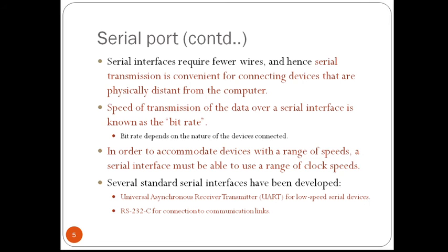After receiving one character from the serial line, the device cannot start receiving the next character until the processor reads the contents of the data in register. As soon as one character is received, the device cannot receive another until the processor reads it. Thus a pause would be needed between two characters to allow the processor to read the input data. Once one character is fetched, it should be given some time until the processor reads that particular character.